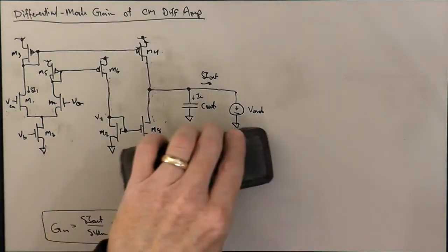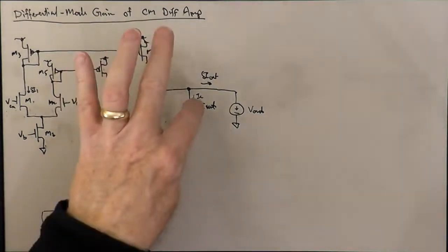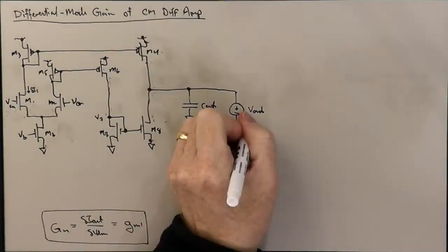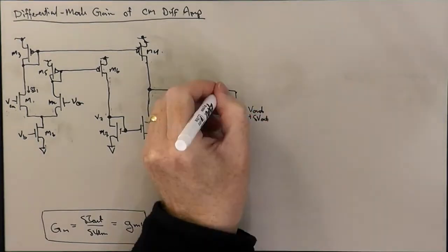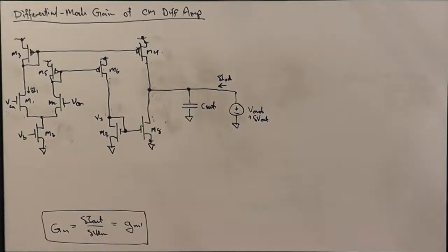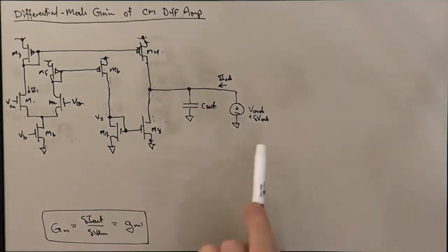And we're going to probe the incremental output impedance of the circuit by wiggling around the output voltage source, and we could consider this delta V out here to be a sinusoidal excitation with some small amplitude at some driving frequency, and ask what is the delta I out, which will be a small amplitude sinusoidal current in this case.